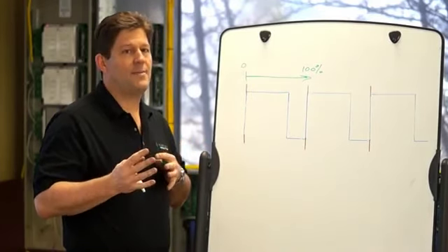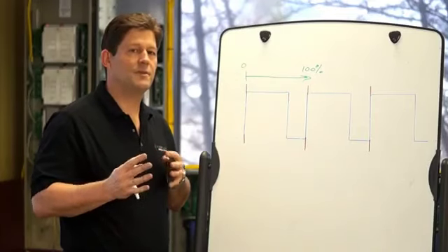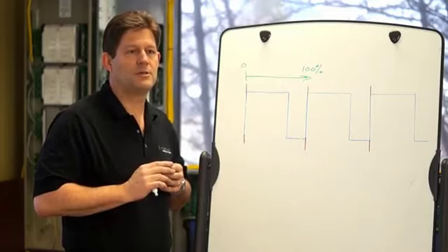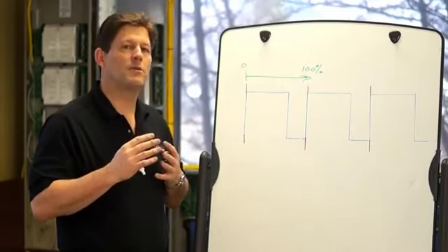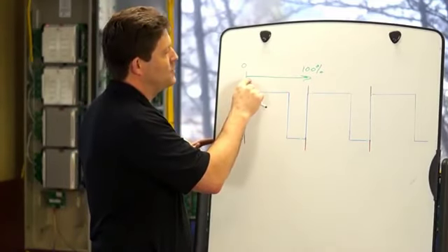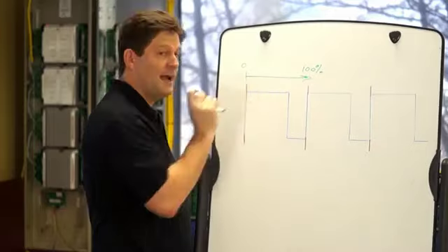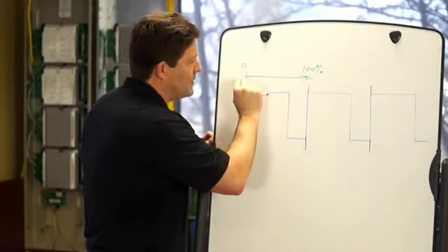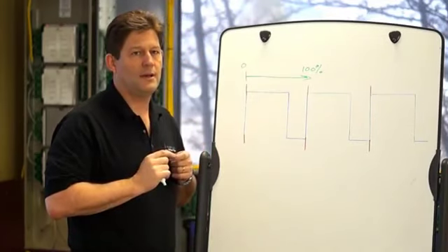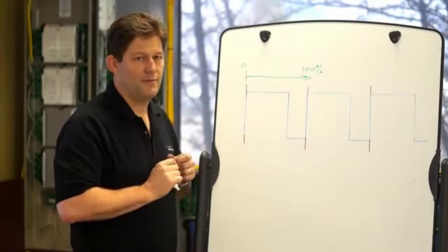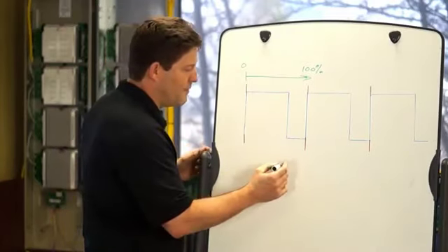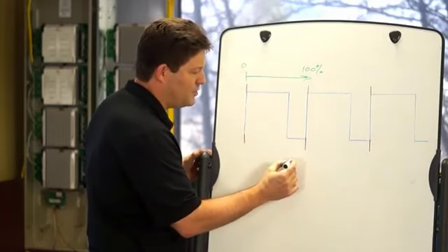Because it is opposite of what you'd expect, you do find from time to time manufacturers of PWM controlled light sources that don't comply and go more with what you would expect. With those light sources, if I apply 0% of the time the voltage, then I will get 0 light output, and I will increase linearly up to 100% or full output when I get to 100% of the time that I'm applying voltage.